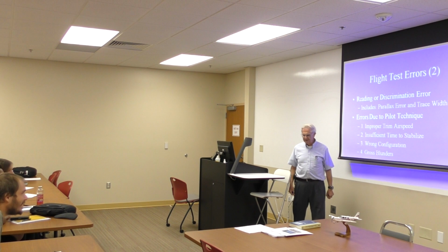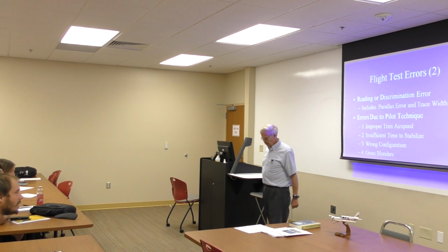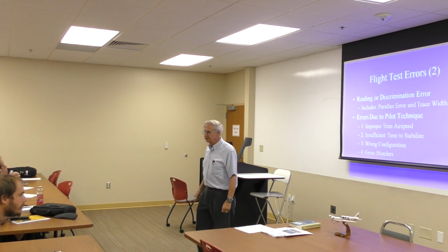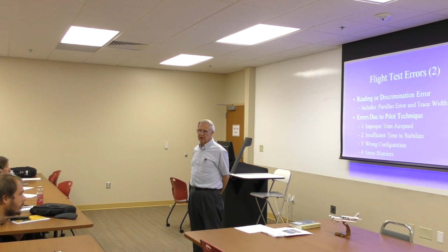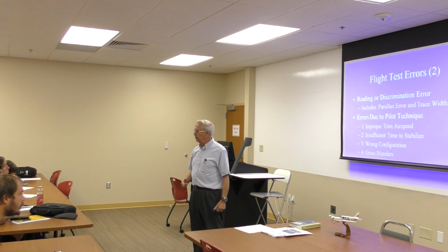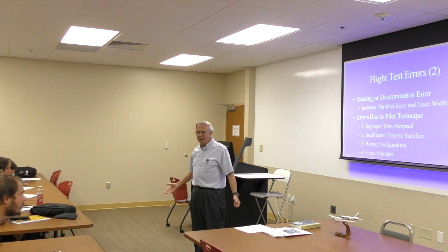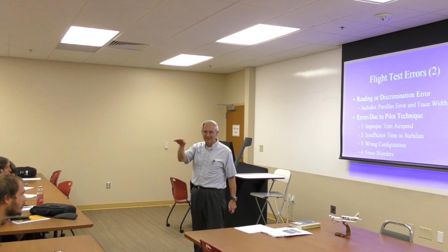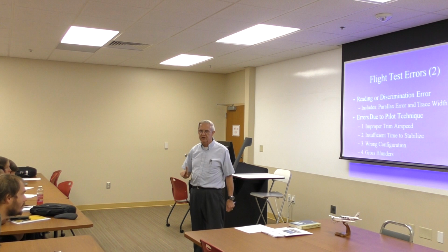Insufficient time to stabilize. This is the other thing I used to hate when I worked in the industry. I just absolutely hated when the magazine writers came to fly in our airplane. Because the magazine writers would always want to see how fast it goes, and they'd climb to altitude, and they'd level off, and they'd immediately read the airspeed indicator. Well, the poor airplane hadn't had time to accelerate and stabilize, so it was always slow.